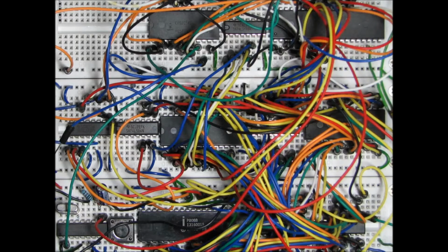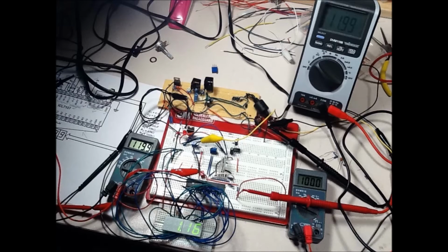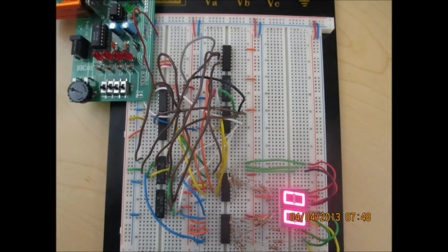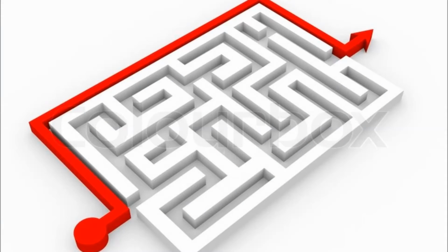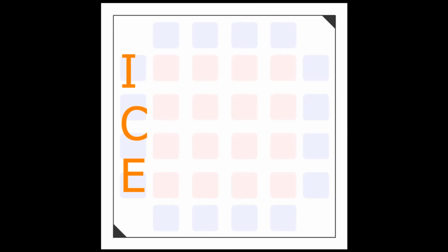These facts can turn into annoying difficulties, especially with combinational circuits based on multiple ICs working together. While testing a multi-chip circuit, error detection can be very troublesome. It becomes harder to find which cable from which IC pin is not attached, which cable is shorted, which part of an IC is burned out or malfunctioned. These steps are taking most of your time, instead of the development process. That's the second issue.